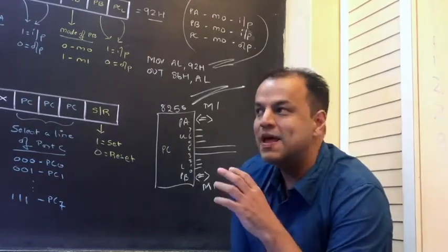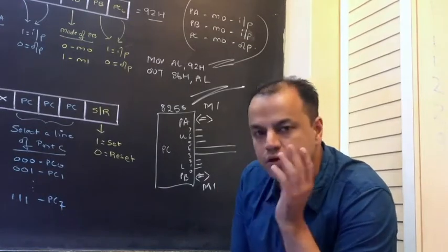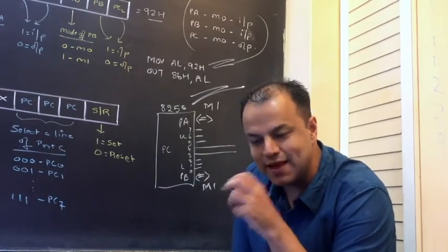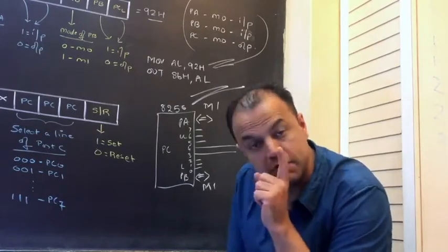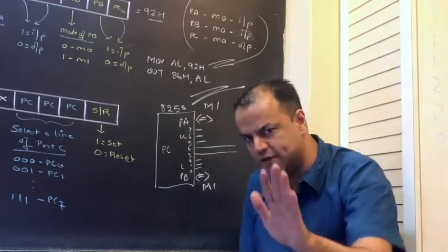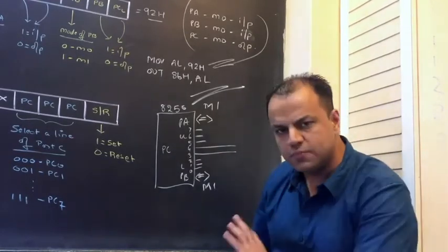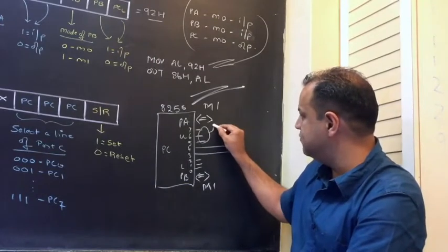So after this, in the next video that I'm going to make, I'm going to show you handshaking in detail. You'll come to know that to do handshaking, any port requires only 3 lines from port C. It needs 4 lines altogether, but from port C, it takes only 3 lines. The 4th line is already available with 8255. Anyway, the point is, port A and port B will take 3 lines of port C.